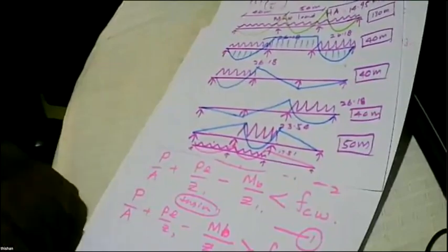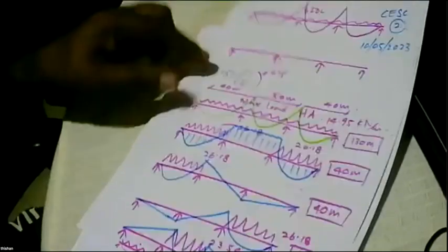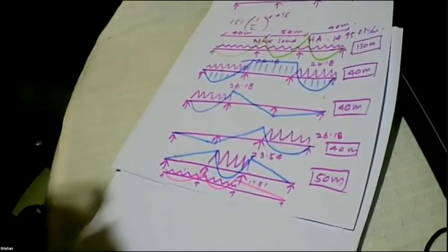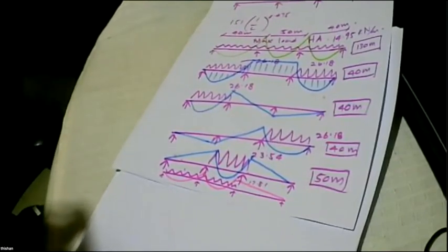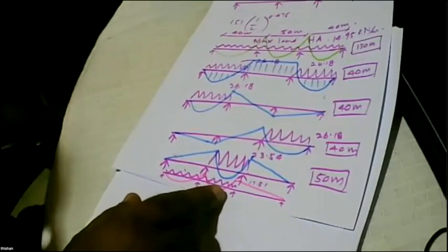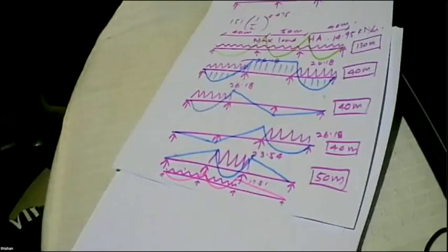So you get so many different combinations. So that's where the problem comes. When it is continuous, there are numerous possible combinations. Not only that, you can even have half the span loaded. So there are so many different combinations, but generally this type of combination will be more critical. So you cut, and not only this, now you can get a mirror image of this also.